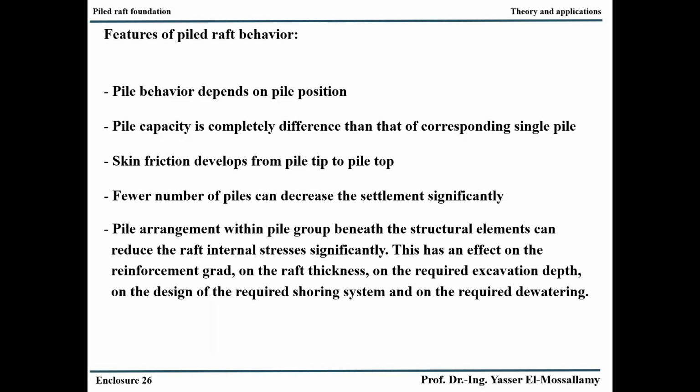Maybe I underestimate it in some areas and overestimate it in other areas. Therefore, it is very important to have a realistic distribution of the pile stiffness below the raft, either in the case of traditional pile foundation or wide raft foundation. The pile capacity is completely different between a single pile and pile groups or a pile raft foundation, and this can also help us to reduce the number of piles and to reach a more economic solution.